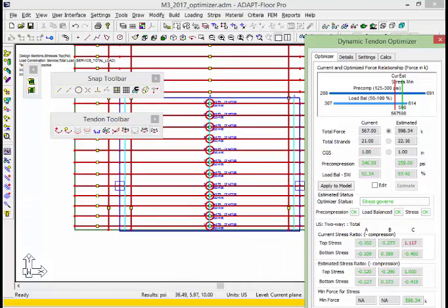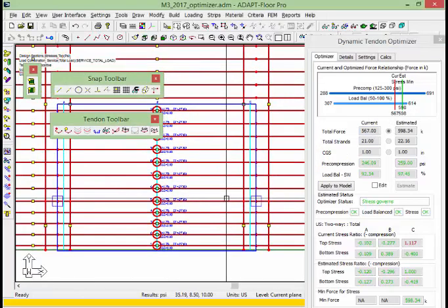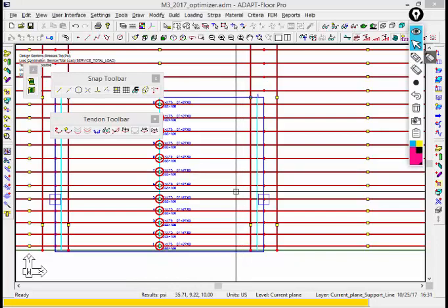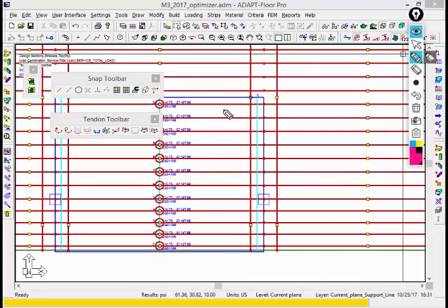And we're back here to where we have a current and estimated force. Now, when we are using the optimizer, the program creates the virtual design sections. We can see that a virtual design cut C is made here. This is one location where we initially had solved the required force, and now we rerun the analysis, and our FEM results show that it's still overstressed.